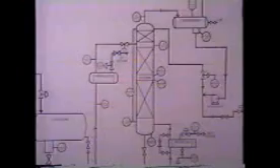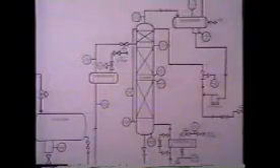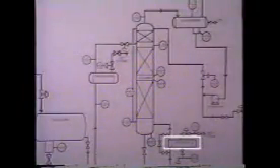However, in some cases, such as when local flooding occurs, it may be necessary to reduce the feed rate as well as the reflux rate. This further reduces the amount of liquid entering the column and helps to reduce the pressure in the column. In addition, the temperature of the column can be lowered by reducing the steam flow to the reboiler. This reduces the amount of vapor in the column.